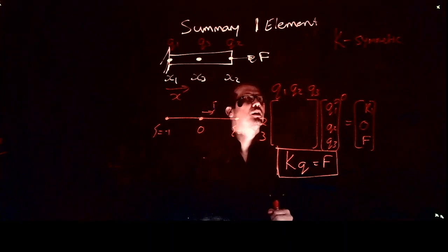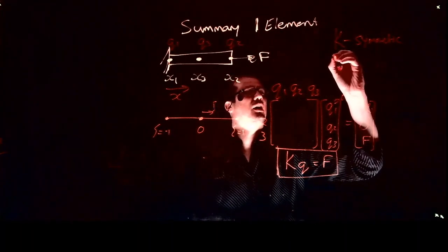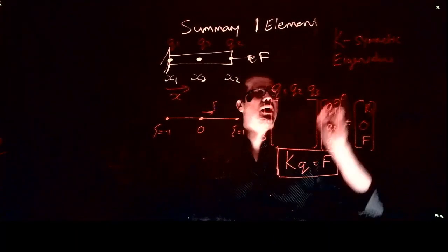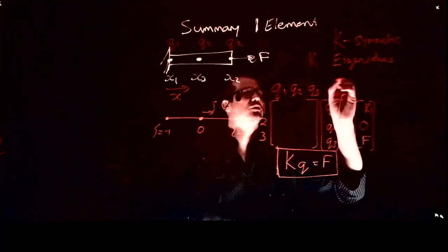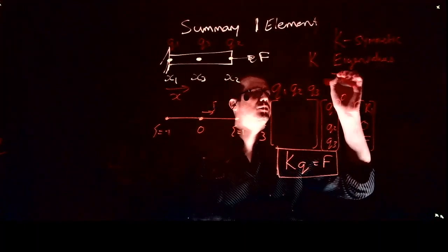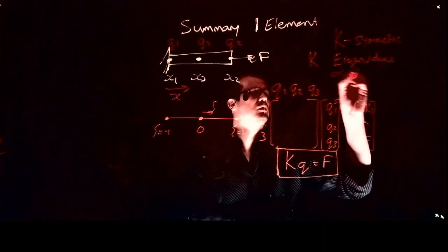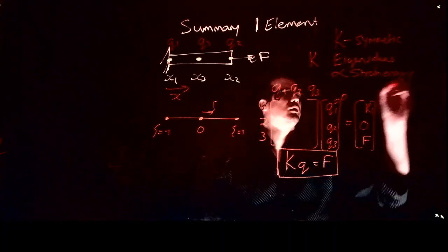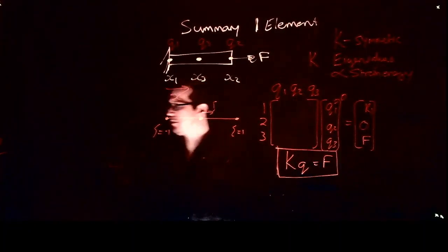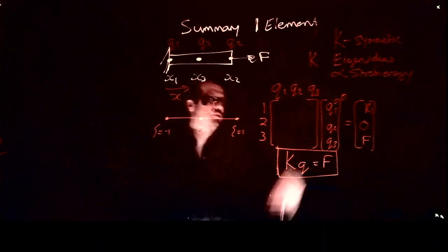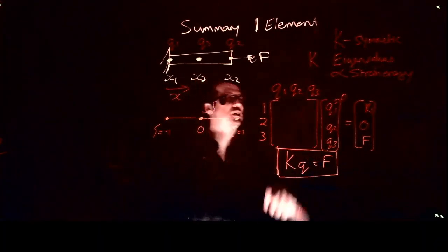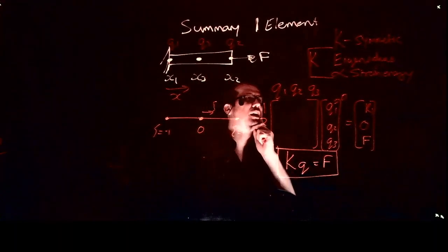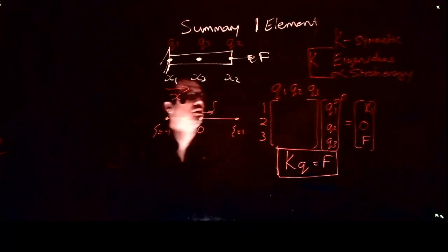That's step one. What we saw is essentially the eigenvalues. The eigenvalues, so the K's eigenvalues, can be interpreted as proportional to the strain energy. Okay, the eigenvectors are associated with the deformation modes. So the deformation that results in that strain energy. So this is what we were able to see with eigenvalues and eigenvectors. Okay, so that is important to understand there.